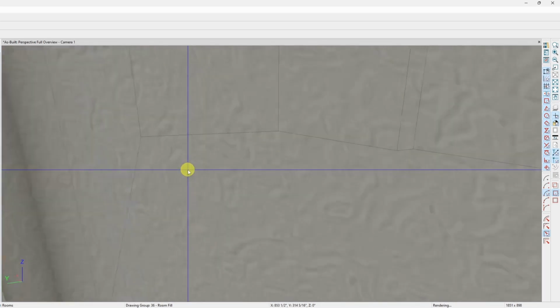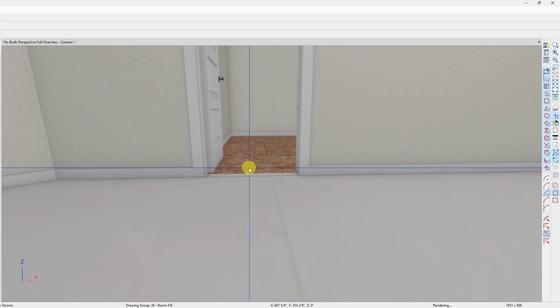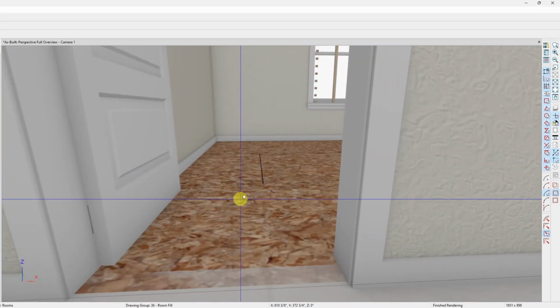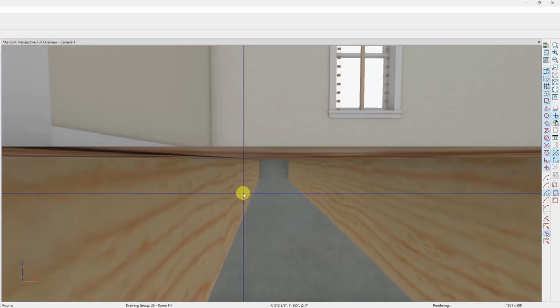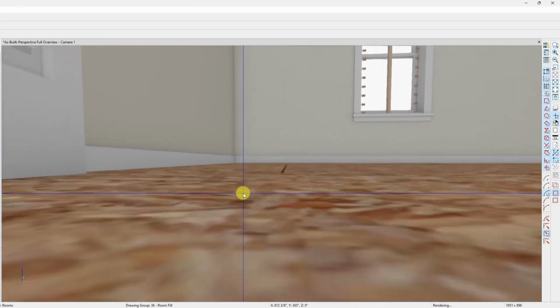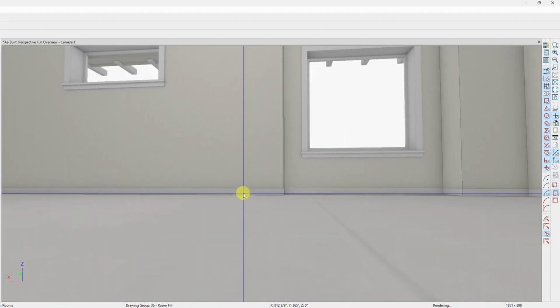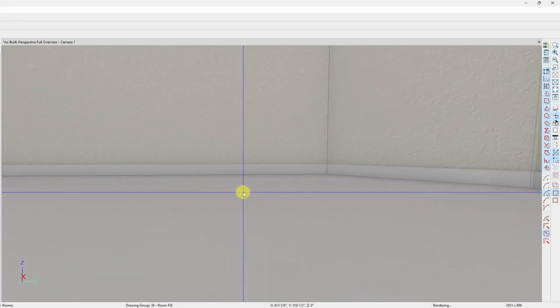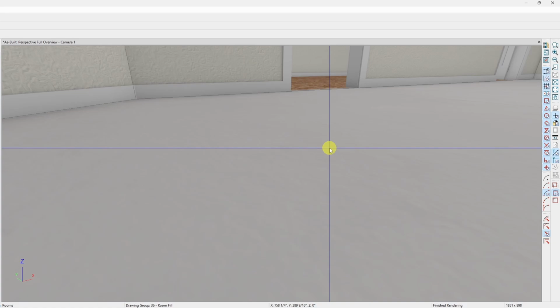This is just to show that we've got a subfloor in here, and I don't know yet, and I'll find out more, if this has also 2 layers when you go into other rooms. Right now I'm just showing a 3/4 inch, and even though it's not OSB, it's the right thickness, and it's a subfloor, so it's doing the job that I want it to do.